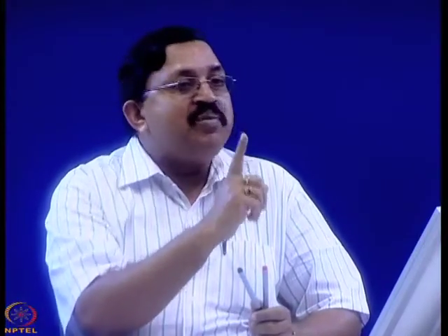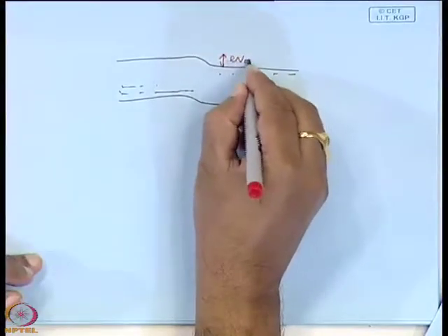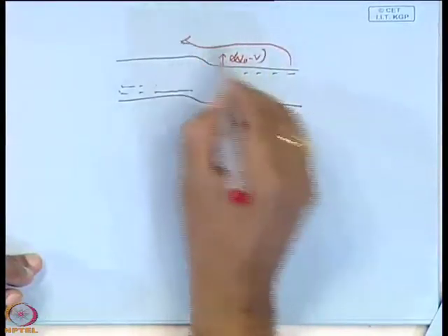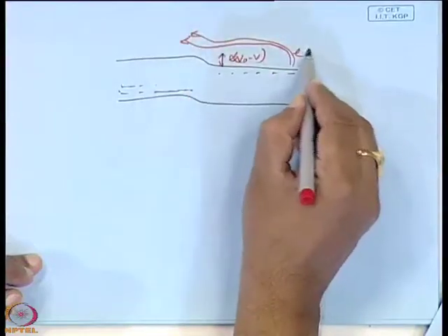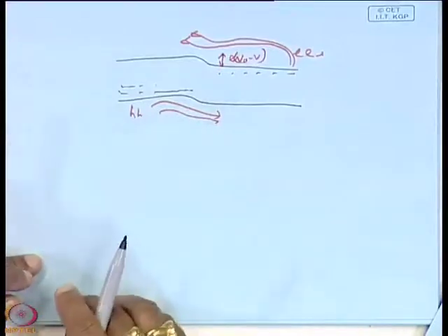Only during equilibrium will there be alignment of the Fermi level. Now, this amount is E V0 minus V. So, diffusion of electrons will take place and holes will diffuse from this side to that side.